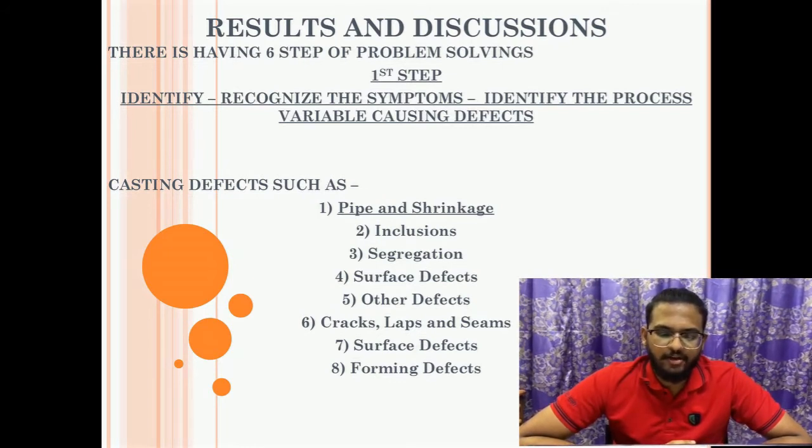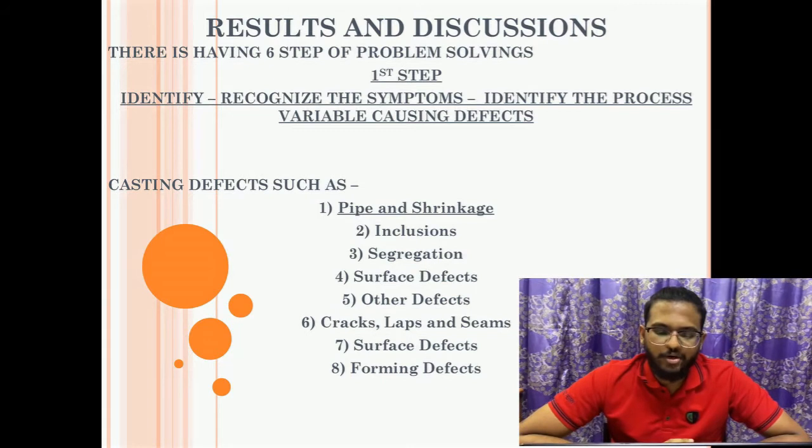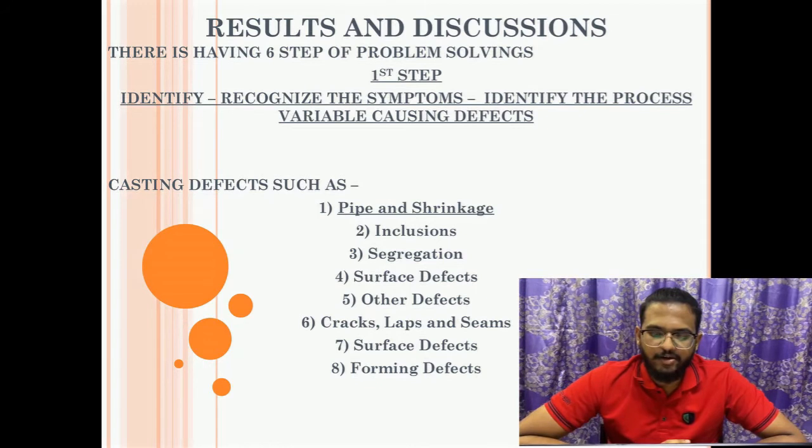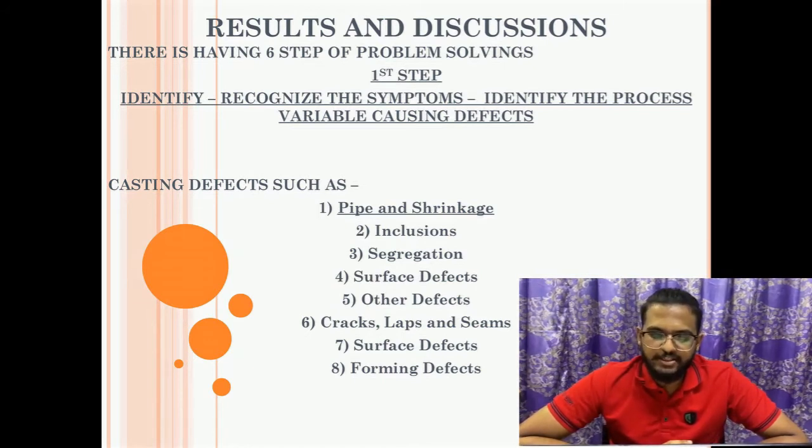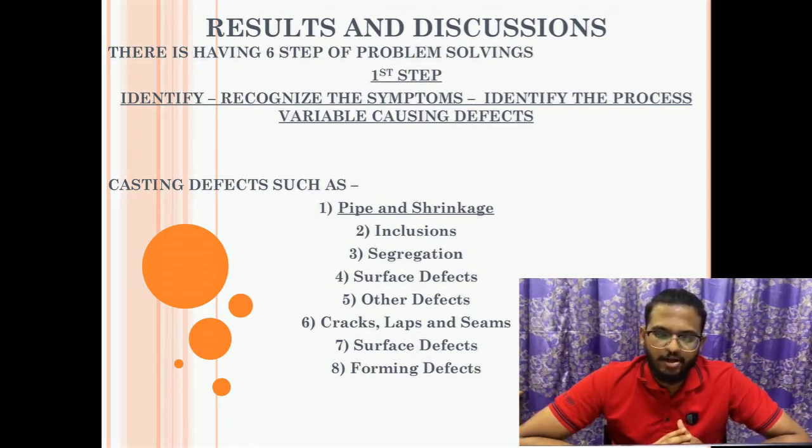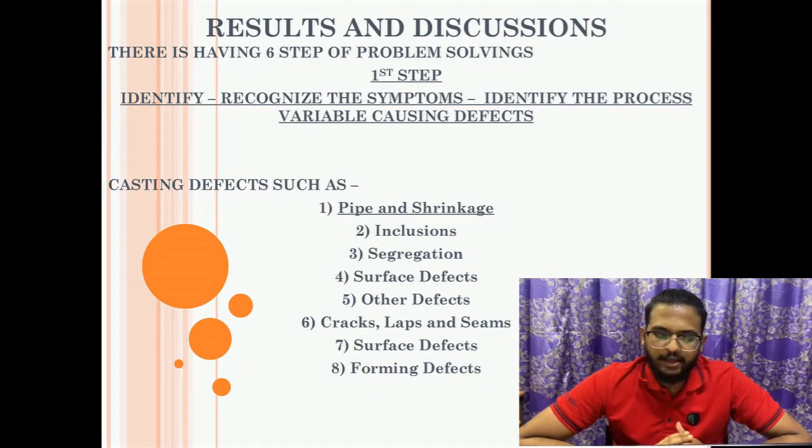The next is inclusion. There are 2 types of inclusion, which are indigenous and exogenous. Indigenous inclusions are small intermetallic particles such as sulfide, oxide and silicates formed by chemical reaction with the atmosphere, while exogenous inclusions are larger, resulting from the accidental inclusion of foreign matter such as broken sections of refractory lining, and can be several centimeters in size.